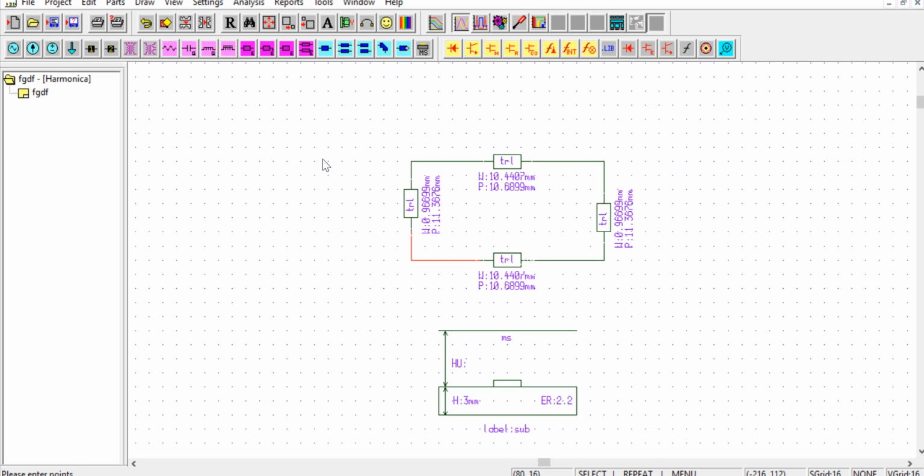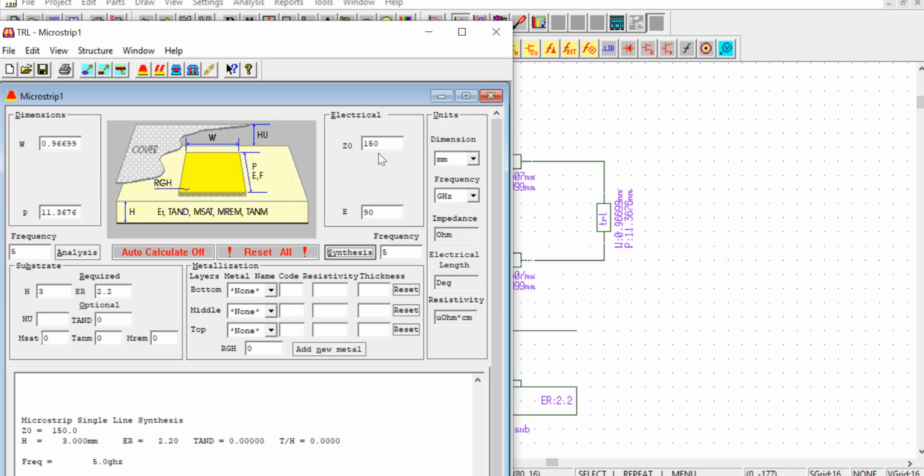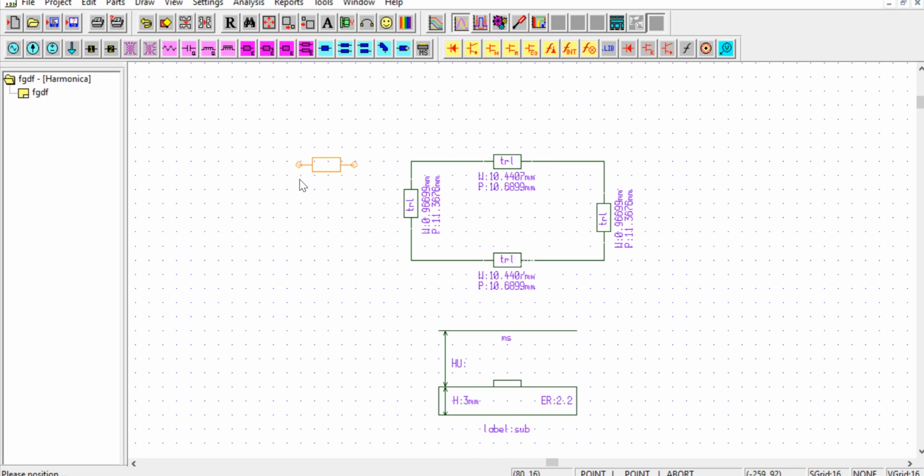So connection is done. Now we need the leg part. The leg part will be of reference 50 ohm, and the length could be anything, no issue, because they are only the connector. For us, let it be 90 only. Synthesize and get the thing.